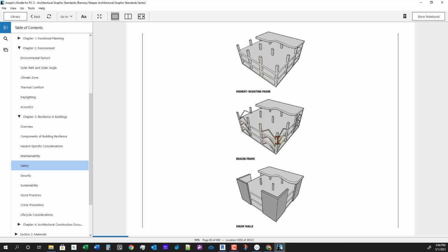In this brace frame, you can see we have these diagonal braces at the corners, and in our building we put them in the middle. So we had them at the ends and then in the middle to resist the loads. And shear walls are basically like beams. The way they describe them is like beams that are cantilevered up from the foundation.